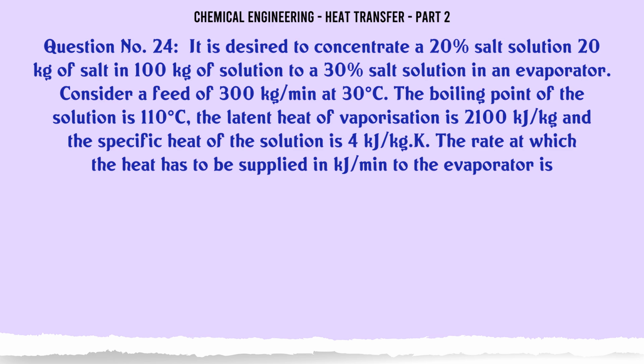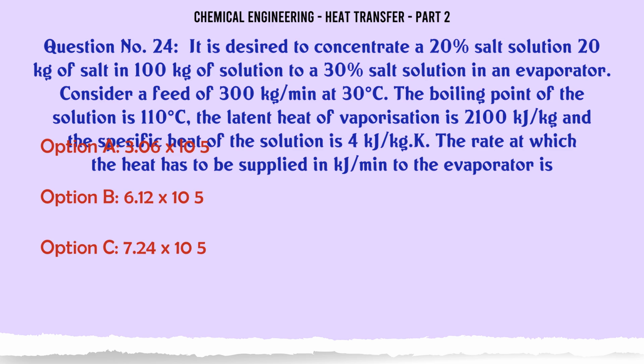It is desired to concentrate a 20% salt solution (20 kg of salt in 100 kg of solution) to a 30% salt solution in an evaporator. Consider a feed of 300 kg/min at 30°C. The boiling point of the solution is 110°C. The latent heat of vaporization is 2100 kJ/kg and the specific heat of the solution is 4 kJ/kg·K.